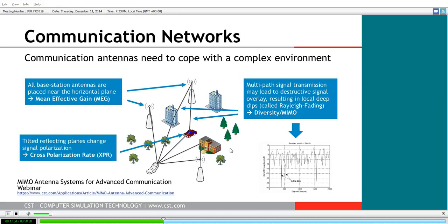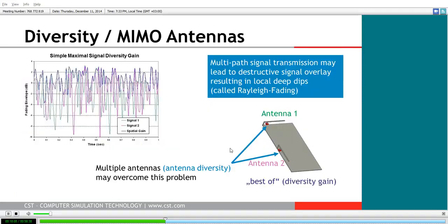The way to combat this type of fading that can occur, what's called multipath or Rayleigh fading from these multiple paths, is to introduce diversity into your antenna design. This is the so-called multiple input, multiple output antennas. So you can see here just a very, very simple MIMO antenna where there's a bit of spatial diversity as well as a polarization shift for these pair of PIFA antennas.